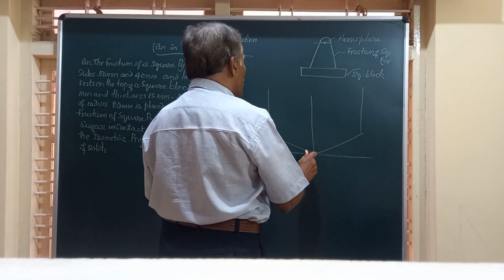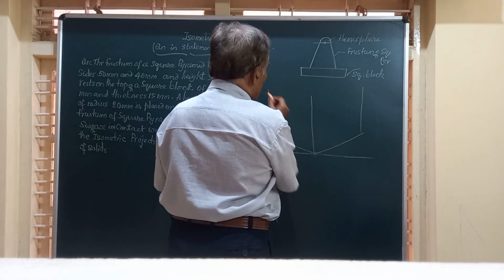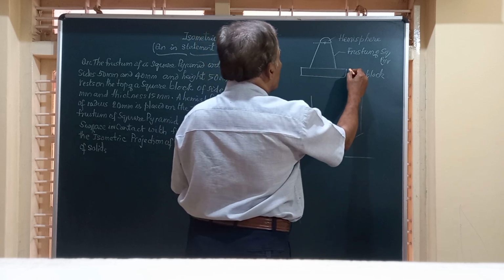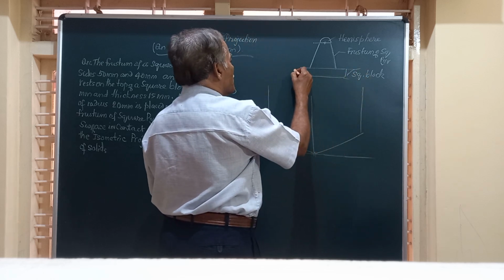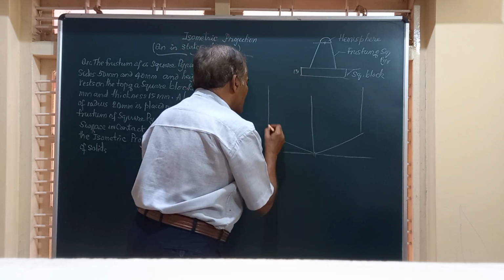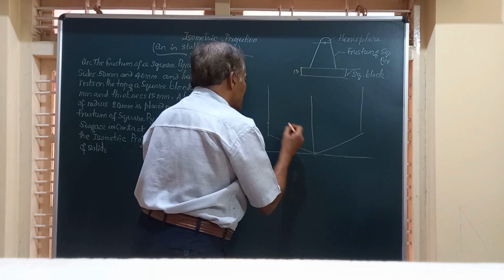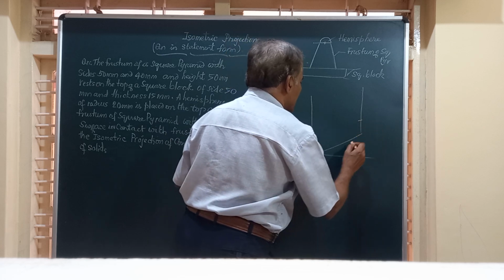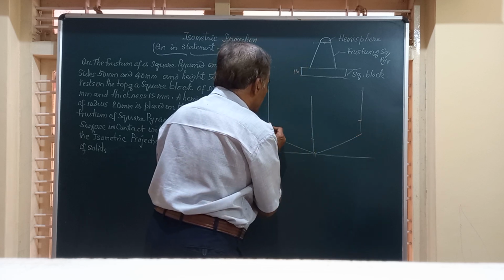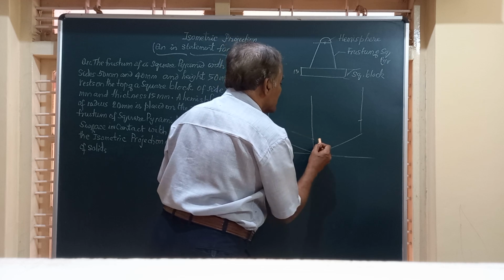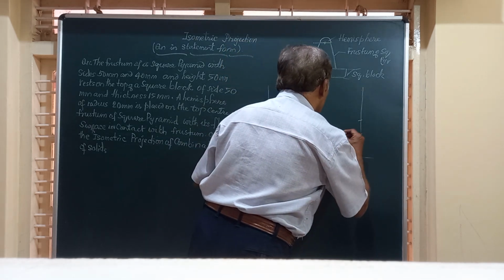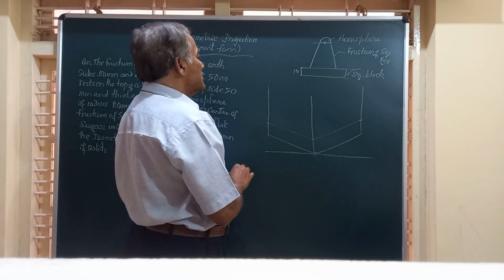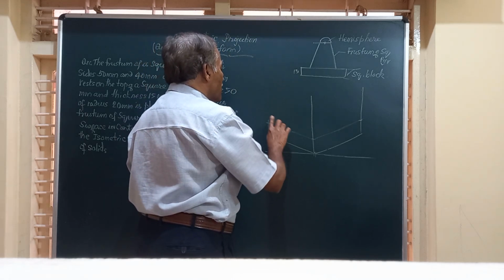So three lines we have drawn. And we will draw lines parallel to these now. The height is only 15, so I will take a height of 15 here, again 15 on this line, 15 on this line. We are going to join them by thin lines to start with, and at the end we will join them by visible lines. Friends, this is how the square block is drawn.